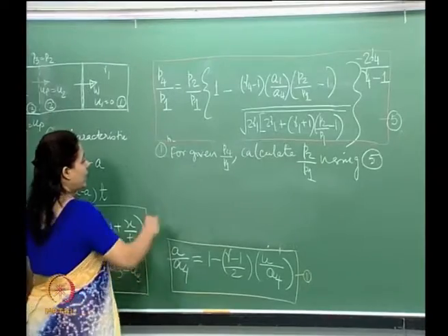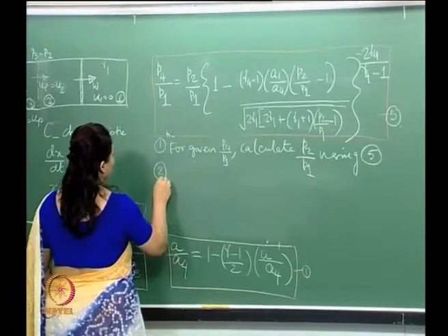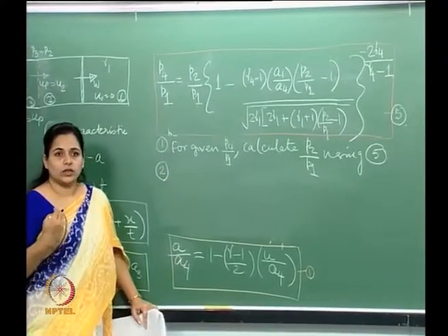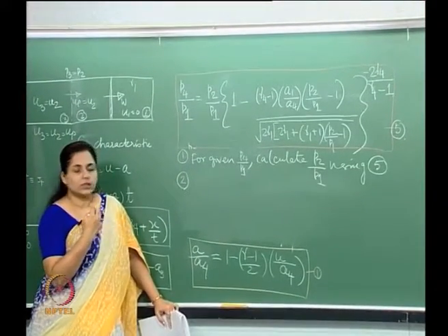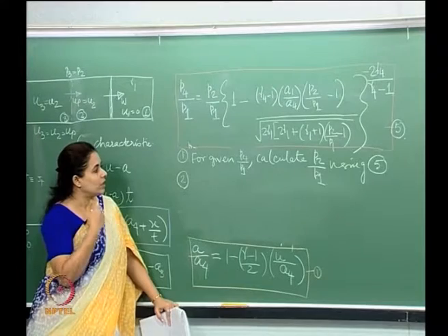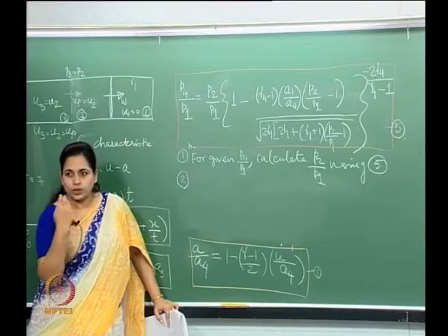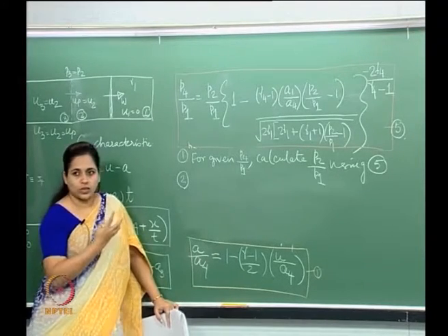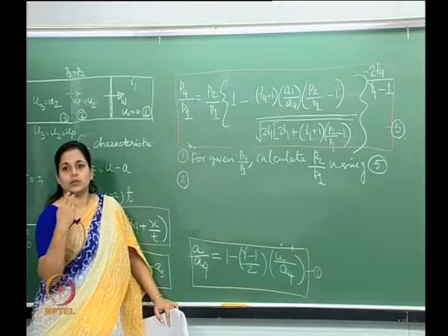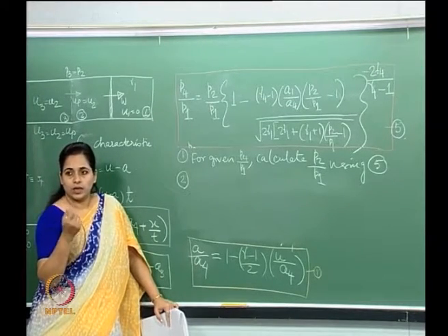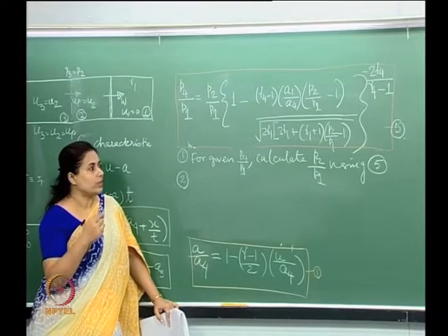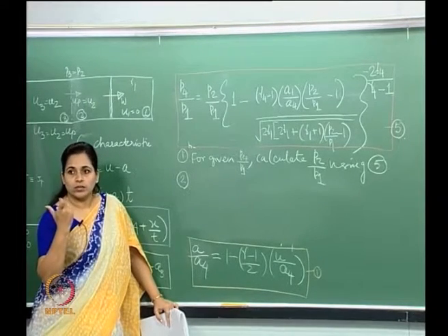And then, as we have already done for shock waves, for an unsteady structure like this, the properties basically depend on the pressure ratio, unlike the steady cases we have done before, where they were dominated by the incident Mach number.